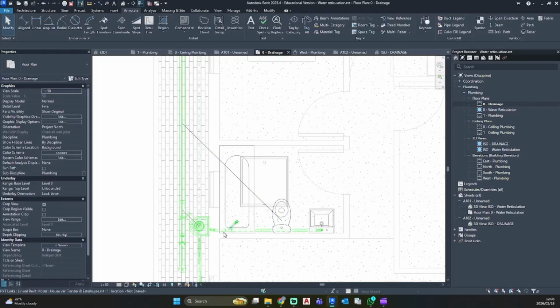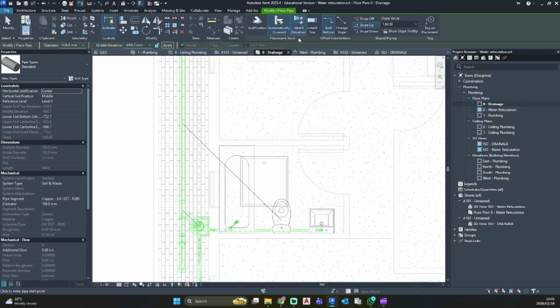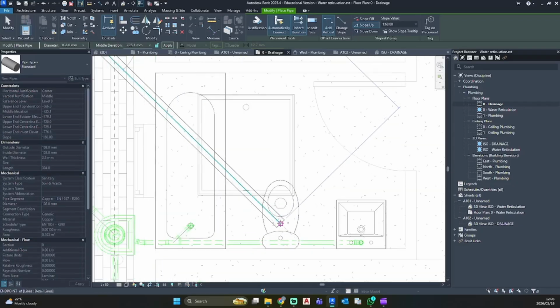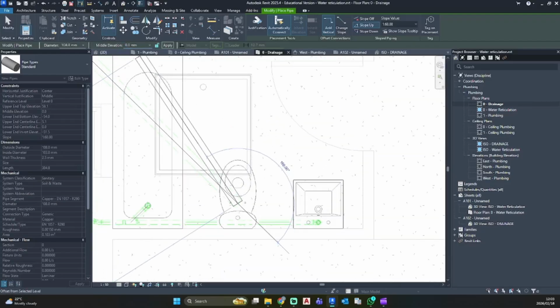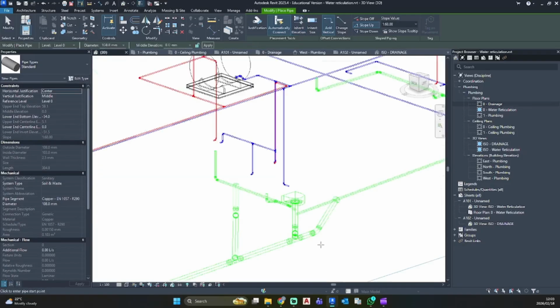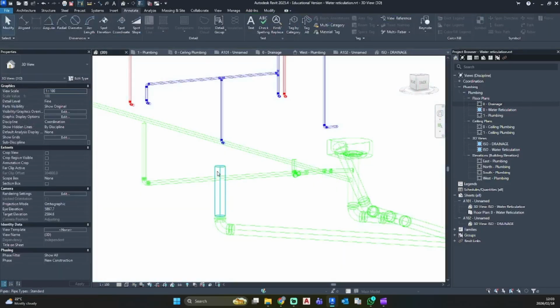So once again, the same as we did here, we're going to select our pipe, create similar, inherit elevation, slope up because we are working back. Selected there, and I'm going to press tab to ensure that I have the intersection of pipes and endpoint of line, and I'm bringing it over here. Let's see. Okay, it made the connection, and now we want this on 0. Apply. And here we have our VC.